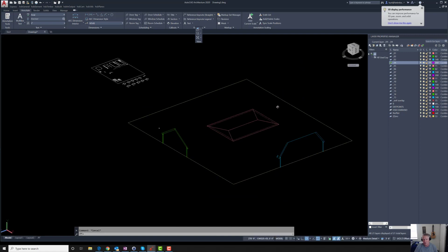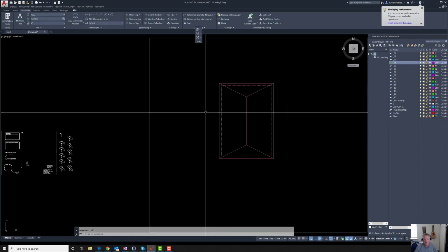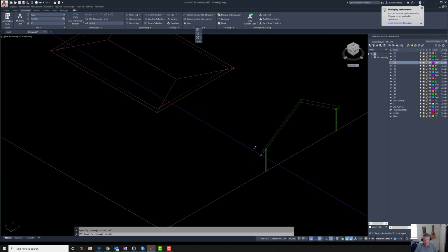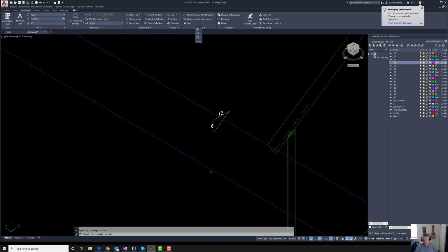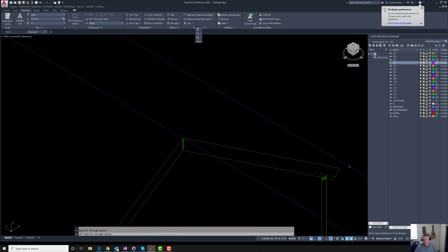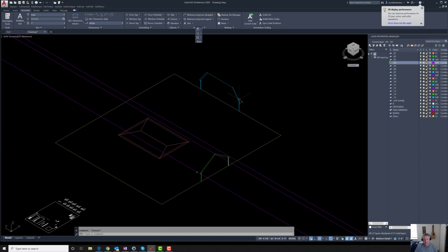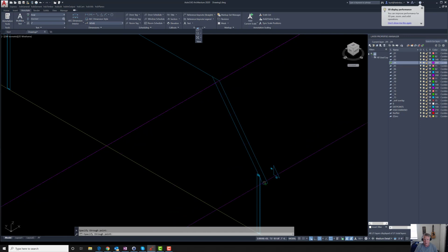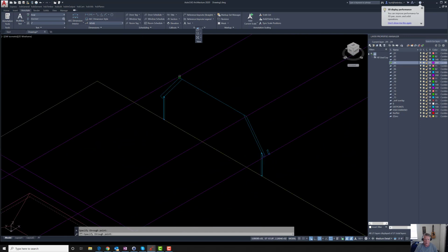So the way I'll do that is to create another roof plan, but this time it'll be a wireframe in 3D. I will do that by working in 3D space, and I will draw some lines that represent the fascia points. This is now a line up in the elevation world, up in 3D. I'll snap one to the ridge and one to the lower fascia there. And I'll do the same thing for the fascia and roof intersections for the 16 and 12 pitch roof.